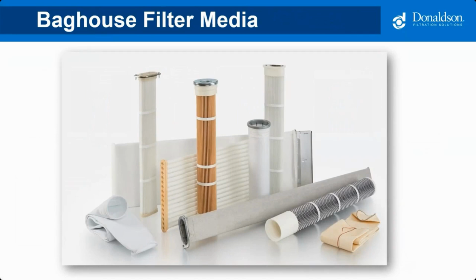Fabric bags are installed over metal cages. During filter changeout, the entire bag and cage are removed from the collector. The used filter bag is then removed from the cage and the new one installed in its place. Finally, it then goes back into the collector. Now imagine doing this process over and over a few hundred times.